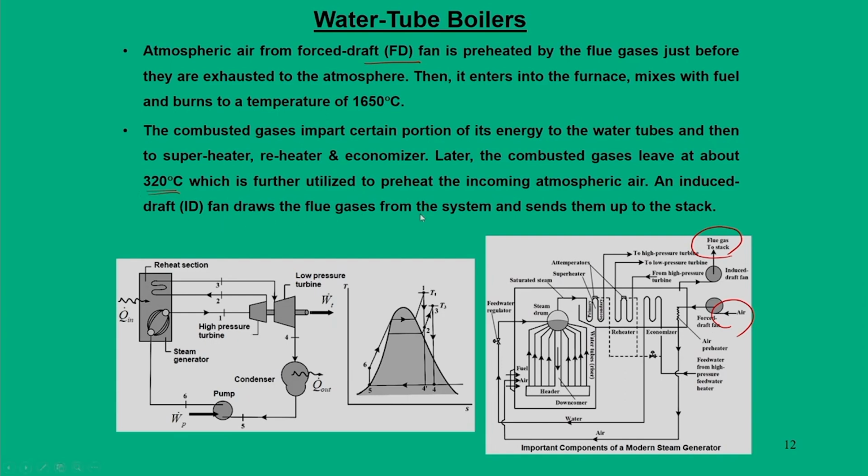The flue gases have to be drawn away from the system and then exit through the stack. Moreover, they have to go to the higher atmosphere, that is, to a relatively higher height. So, that is the reason we require an induced draft fan.